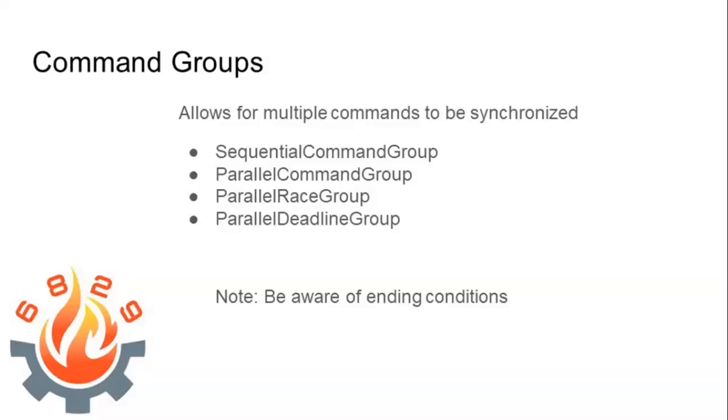Just remember with default commands, you can't interrupt, right? So if you have any one of these commands and they don't end for some reason, if the first command to lift never ends, then your second and third command are not going to do anything. They're sitting and waiting for that first one to end.